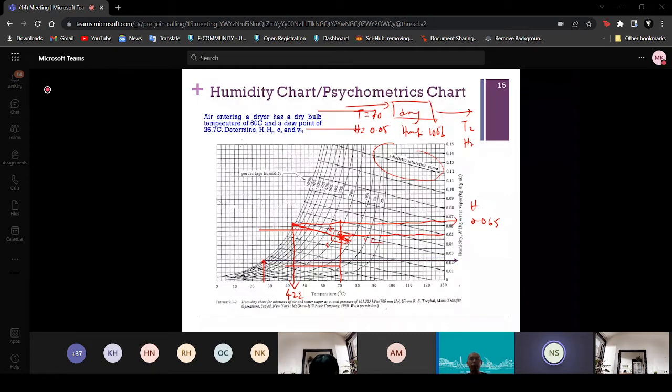So here, when they are humidified at 100%, okay, if it says humidified 100%, whereas earlier it was 90%, you can put T2 and H2. But when it is humidified to 100%, you can change from T2 and H2 to what is also called TS and HS, because it is resaturated. 100% is saturated, so you can make these TS and HS. A different symbol, also known as TS and HS. So here it becomes TS and HS, because they are at the saturated state.